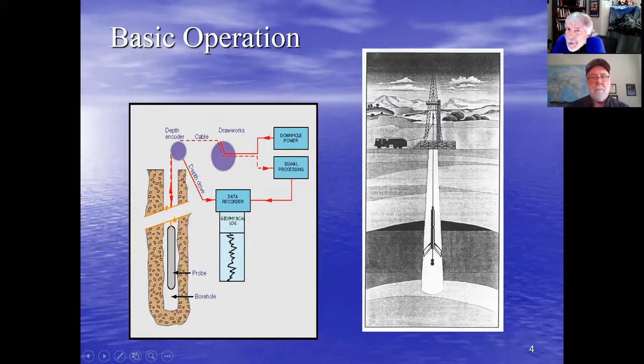The simple basic operation of borehole geophysics is you set up with a truck or some sort of tripod on surface. You're running your cable down your borehole, and remember, this can be both cased and open hole. Different tools, different processes for recording in the different environments. Coming downhole through your various lithologies, you have your sonde down here. In this case, we're looking at a dipmeter that's recording the dip of the formations.